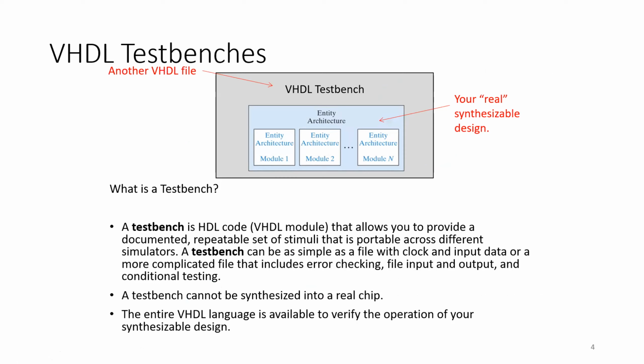It is going to give you a waveform of mapping between the input and output. So it cannot be downloaded to your hardware, but it is just for testing. But it is more sophisticated than the waveform, because in this one I can put some logic in the input, for example. I can put some conditions for the input to go high or low, testing. All of those are extra features that are available in test benches.